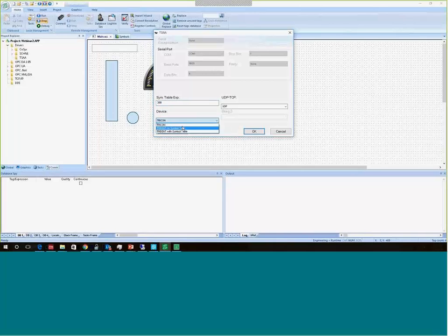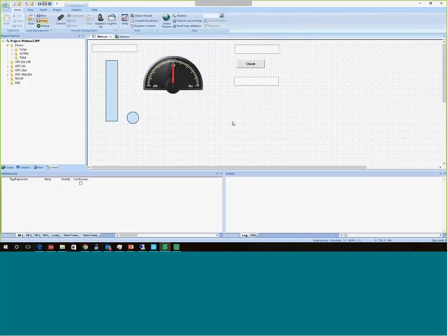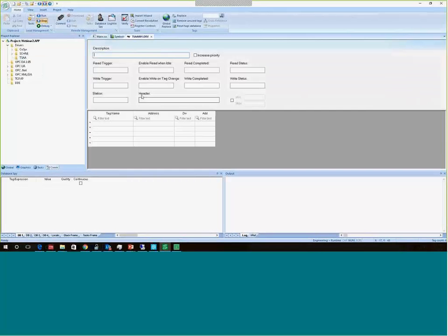This one that I have is the Trident with symbol table. And then I'm going to right-click and insert a driver worksheet. So that's the standard driver sheet where we have full control of our communications, full feedback of our communications.